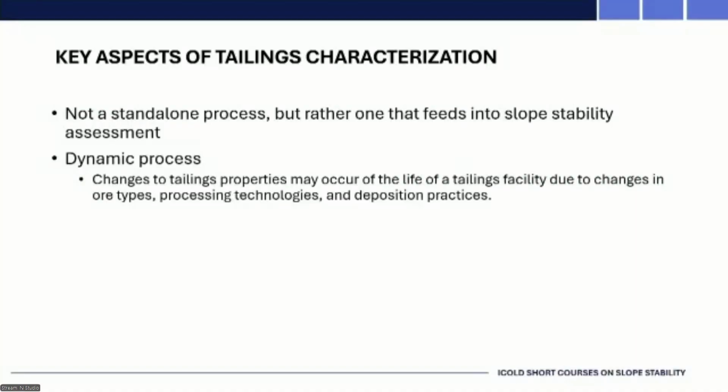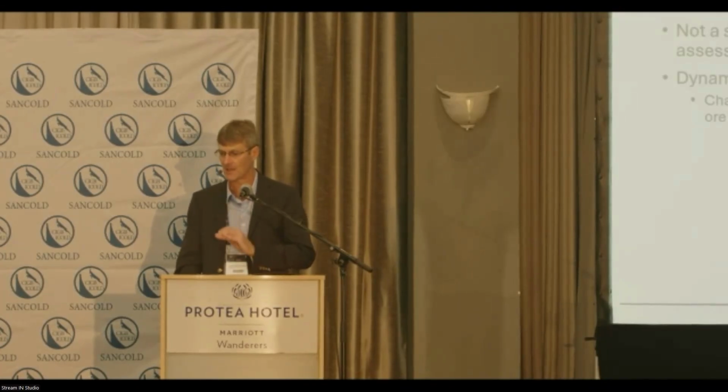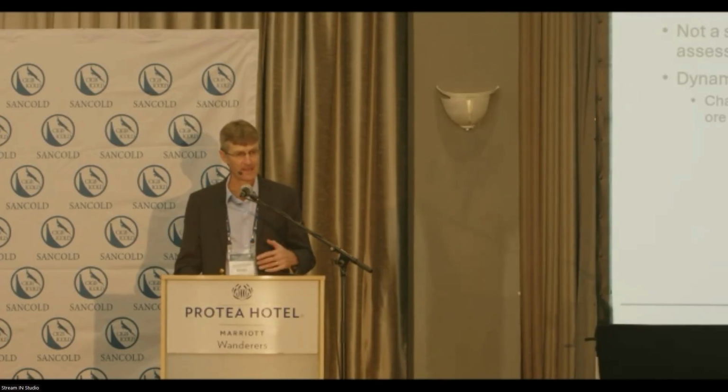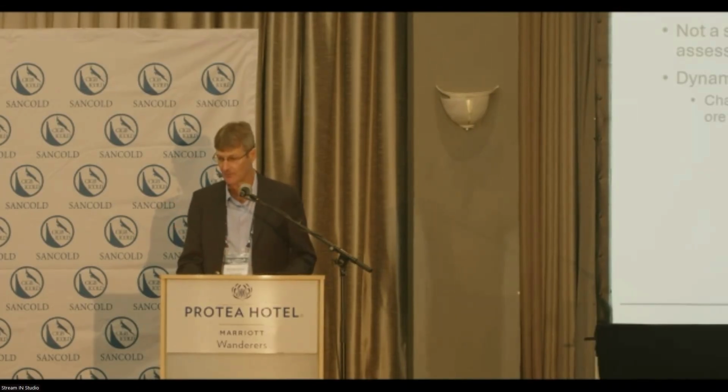So it's not a standalone process. It obviously has to feed into the slope stability analysis, and it's dynamic. Your tailings dam is not a static structure. A water dam typically is designed, built, and it's more or less a static structure, apart from the water level rising and falling. Tailings dams are not like that. They keep changing. Your ore body can change. The process plant processes can change. And then your deposition practices can change. And so all of that affects the behavior of the facility, and what you designed up front may be quite different from what actually gets built and what you have to evaluate in terms of performance.